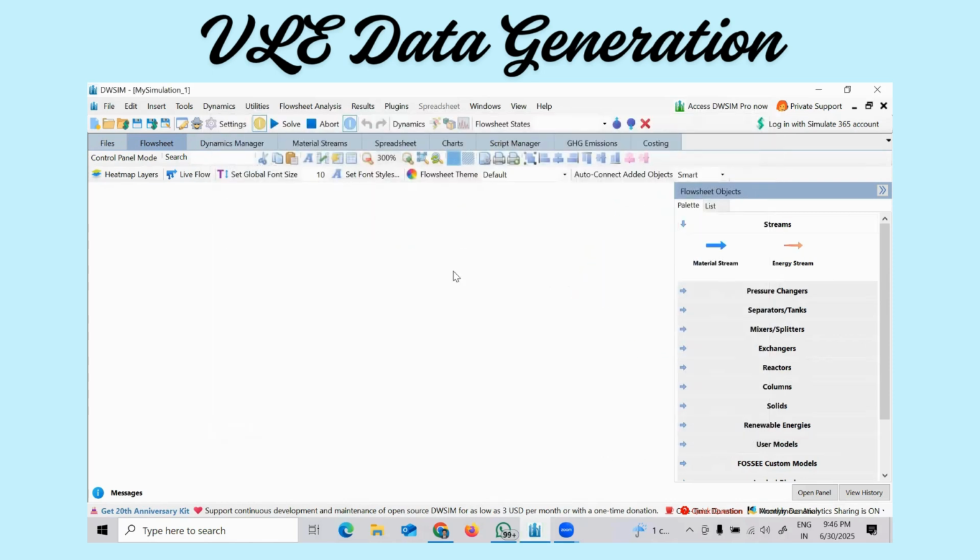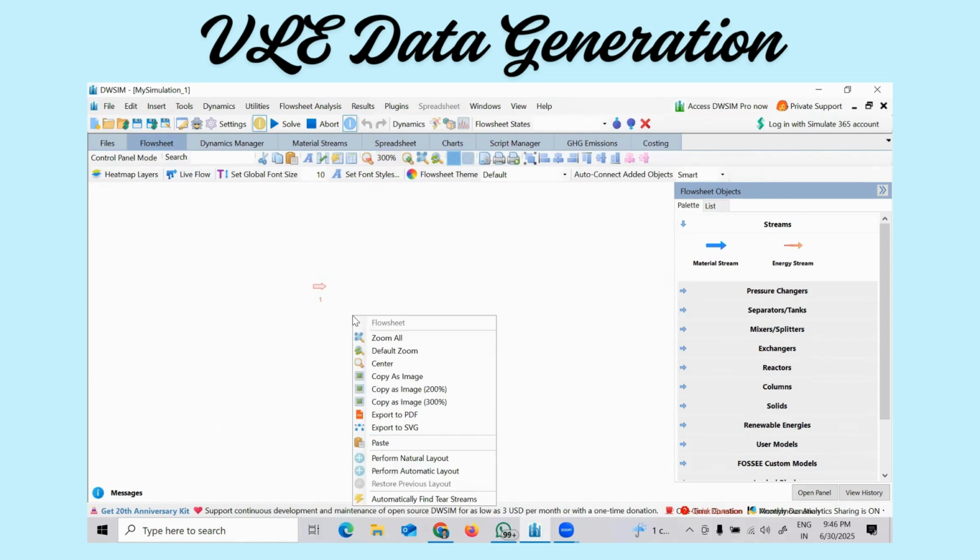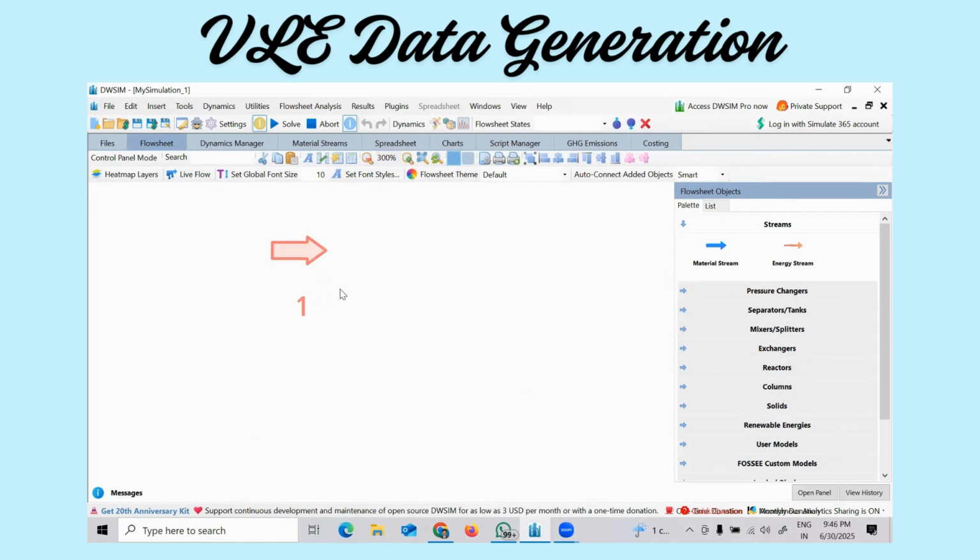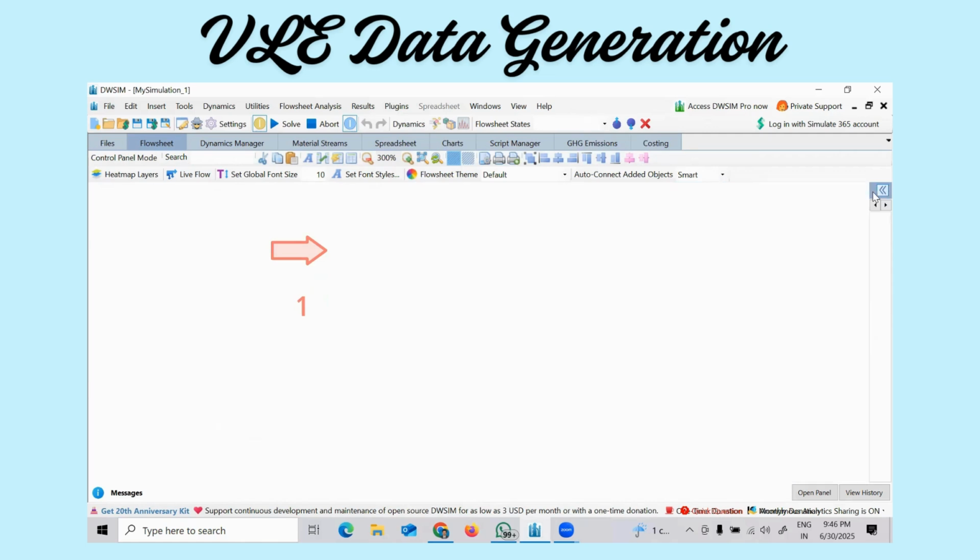So we are out of the system configuration window, having given the basic inputs to start building the flowsheet. Now I will take a material stream from this place and then keep it here, right? And then I right click here and say zoom all. That means this becomes a little bigger.